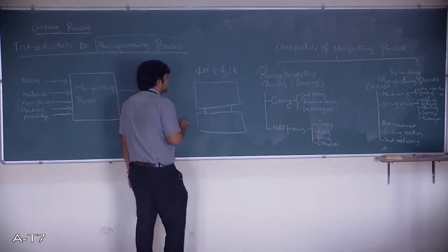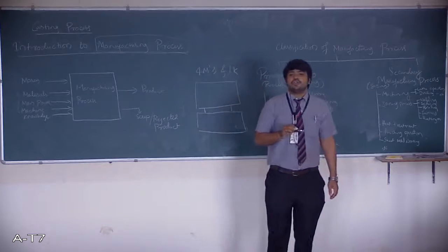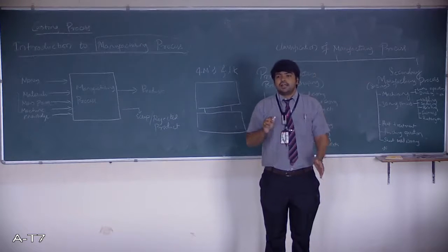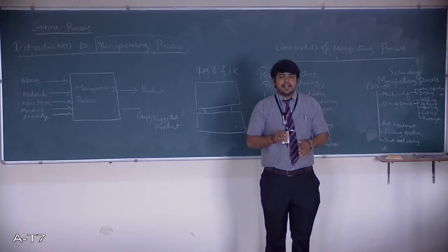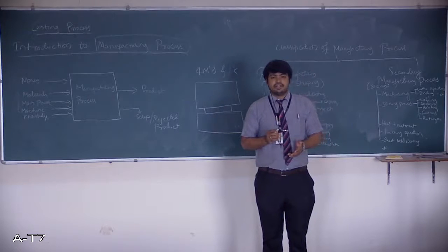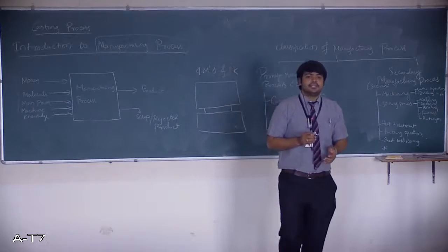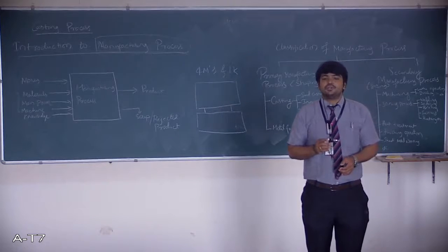The ingots are passed, and the thickness of those ingots is reduced and the volume will not change. Because of that, the length will increase, and thus we get different types of objects by just reducing the thickness. Like plates, we get sheets, we get foils. Likewise we get metallic objects of different thickness and different length. That is what we call rolling.